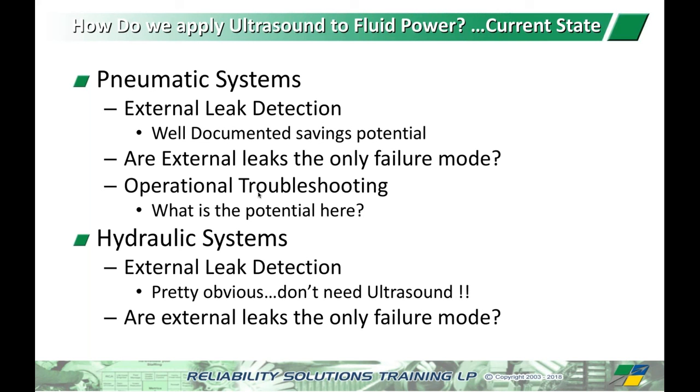Anyhow, that whole process for each line was controlled by, I want to say, about a 3 foot by 3 foot pneumatic panel with a bunch of solenoids on it, and basically directional control valves, fully automated. And when they had a problem, the standard practice that they developed was to change that whole panel. It was quicker to do that than try to troubleshoot it in place.